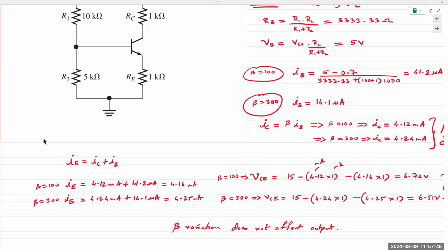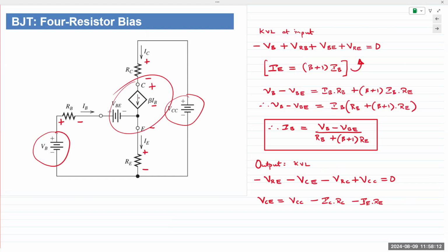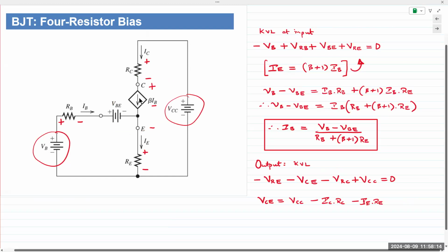So no matter what kind of circuit or what kind of amplifier you're faced with, always think in terms of Ohm's law, KVL, KCL. Those are the only three equations you need to think of. That's it. The transistor model could be different. In this case, we used a simplified model where we have a transistor model as a current dependent current source, right? Because the output current depends on the input current, beta IB. But everything else about the circuit is still the same.